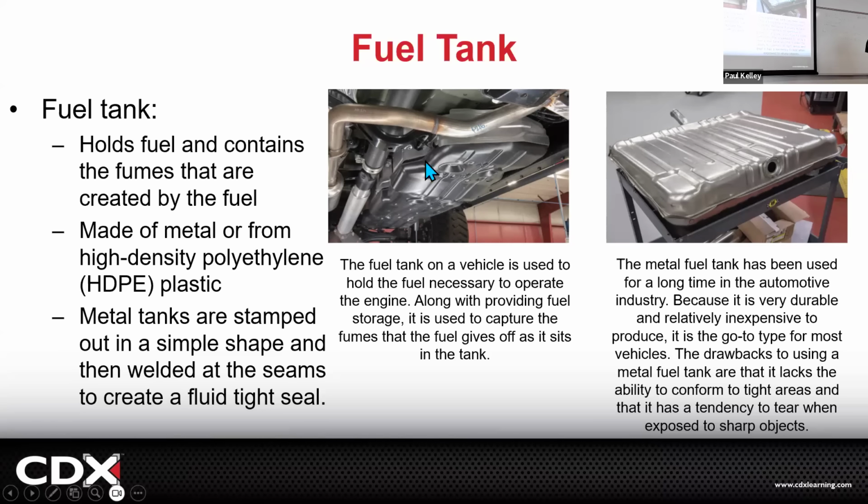So metal fuel tanks are probably mostly going away. I don't really see those anymore. The plastic, loosely HDPE, is the standard. If we're worried about it getting punctured, we're probably going to put a skid plate on there. Makes a lot of sense. Additionally, a lot of times we're going to have a whole vapor collection system called the evaporative emission system, and I do intend to at least loosely introduce that before the end of class.